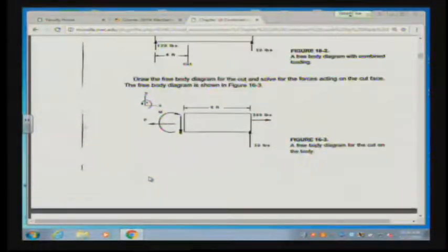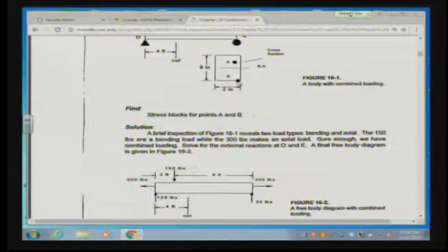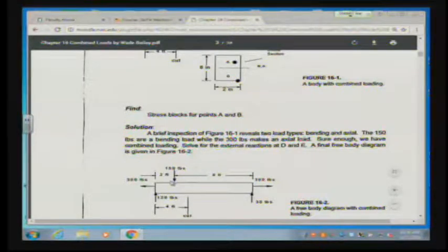All right. Now, continuing with that idea, we can find our sigma at point B, and we can find our sigma at point A. Now, I had said that B was going to be in tension and A in compression, but now I can see that that is the opposite because this is actually a downward acting force.